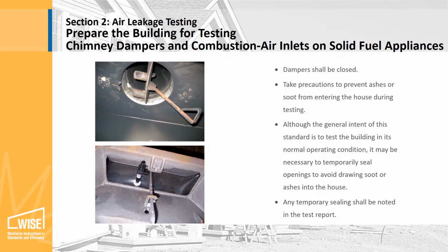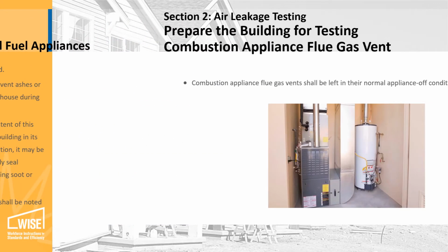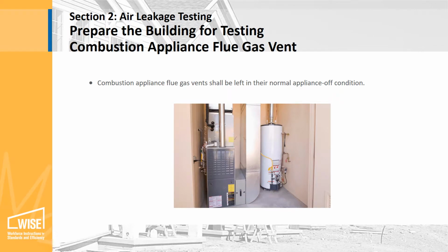With depressurization of the house, it is possible to draw ashes or soot into the home through chimneys, even if the damper is closed. Take extra precaution in these situations by temporarily sealing these openings, and note this in the test report. Combustion appliance flue gas vents shall be left in their normal appliance off condition.